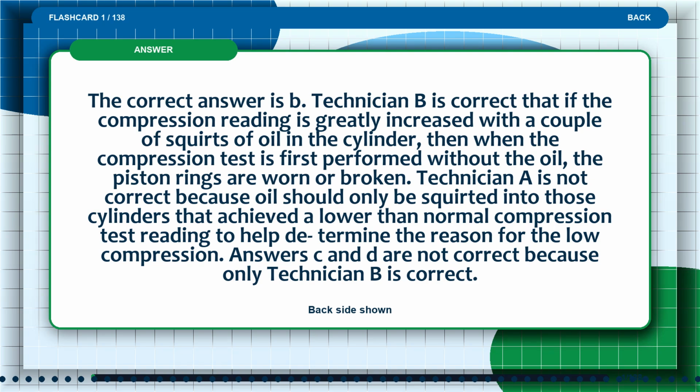The correct answer is B. Technician B is correct that if the compression reading is greatly increased with a couple of squirts of oil in the cylinder, then when the compression test is first performed without the oil, the piston rings are worn or broken. Technician A is not correct because oil should only be squirted into those cylinders that achieved a lower than normal compression test reading to help determine the reason for the low compression. Answers C and D are not correct because only Technician B is correct.